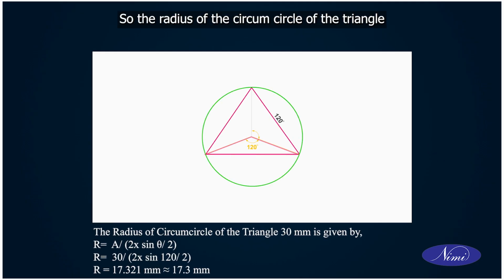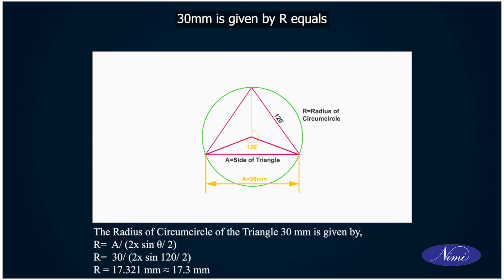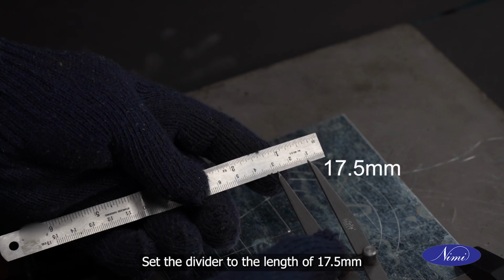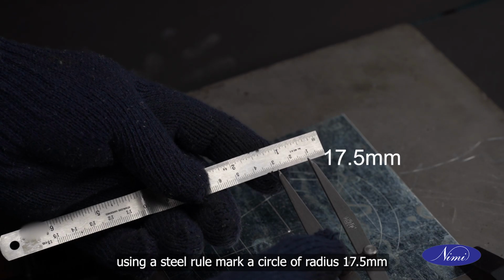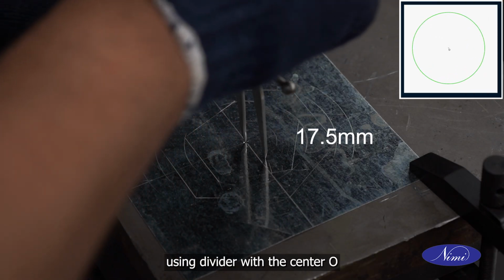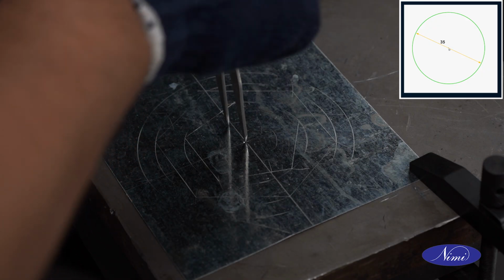So the radius of the circumcircle of the triangle of side 30 mm is given by r equals a divided by 2 into sine theta by 2. R equals 30 divided by 2 into sine 120 by 2. Therefore, R equals 17.321 mm, roughly 17.3 mm. Set the divider to the length of 17.5 mm using a steel rule. Mark a circle of radius 17.5 mm using divider with the center O.